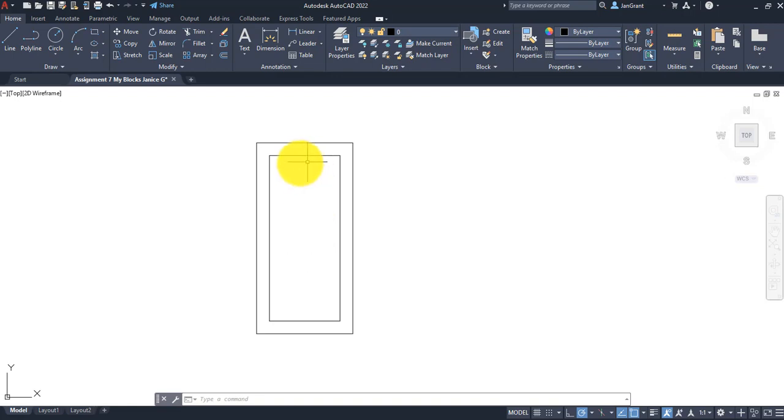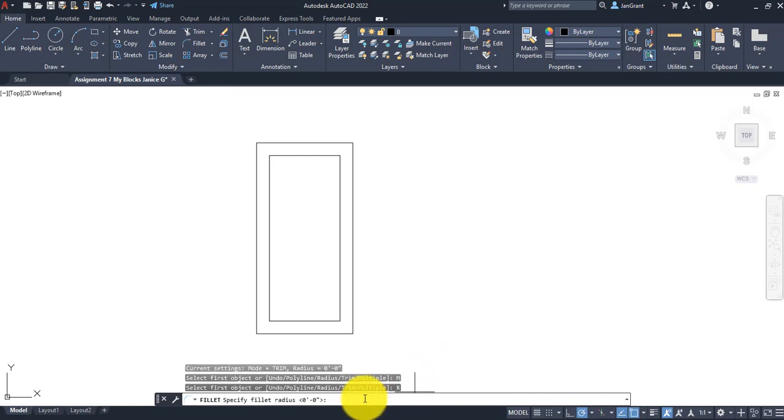It's funny. So now we have a fillet. We have 4 fillets, but the top ones are bigger than the bottom ones, but we can just do it all at one time, right? So we'll come up to the top here and click on fillet right there, and then come down to the command line and click on multiple, and then click on radius. The first radius is 6, which will be the 2 top ones that are big, so I'll type in 6 and enter. And I'm going to click on this line at the left side and this one at the top. Then I'm going to click on the top one at the top and the one on the right hand side.